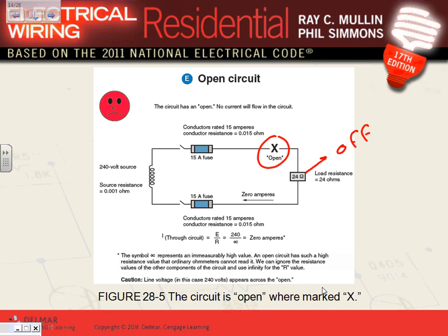So if it's a single-phase system like this, what's going to happen to the 24 volt? Nothing. Okay, but take this. Here's my neutral. I brought my neutral here. And here's my neutral up here. And I have a load. This load now needs a neutral. And I brought another load right here, another 24. Okay? Oh, they're sharing a neutral, right? Take this. What happens if you open the neutral?